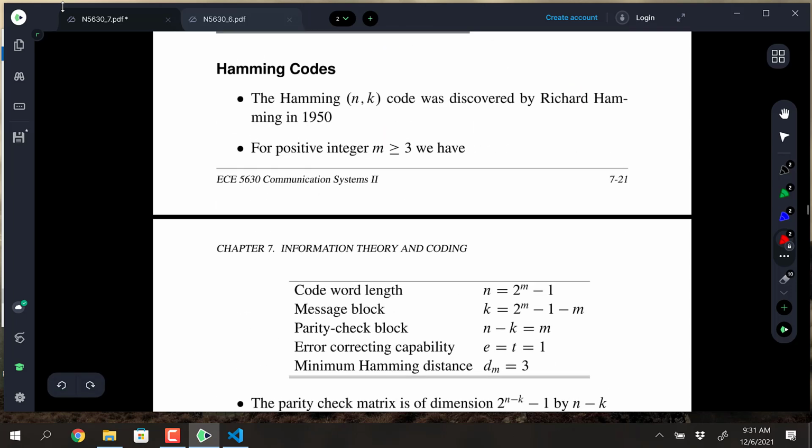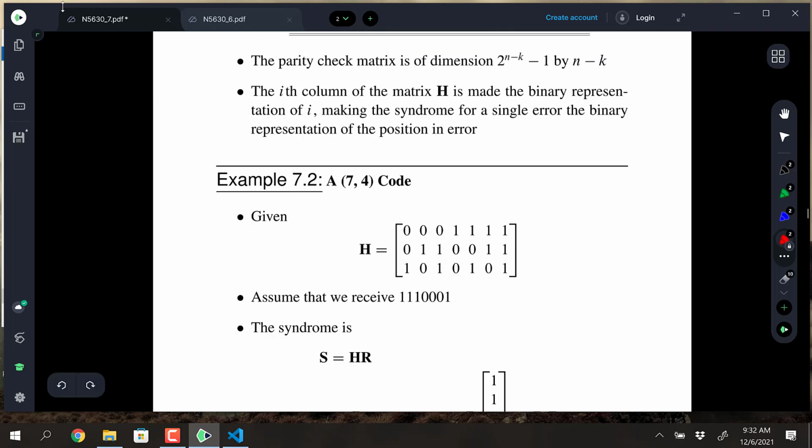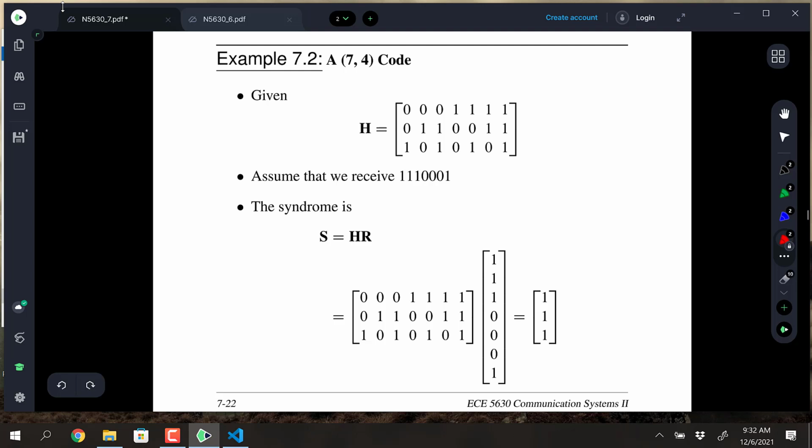Sorry, going back, so that can only correct one error then? Yeah. Because you'll either get all zeros, which means no error, or you'll get something which will indicate one of your bit positions is wrong. Because H needs to then have every combination of non-zeros as its columns. Yeah, that's right. So this is weak. It only can correct one error in this setup. Yeah. That seems not very good. It's not very good. It's a Hamming code, though.